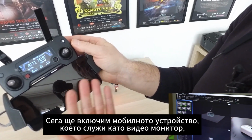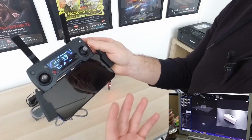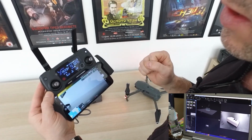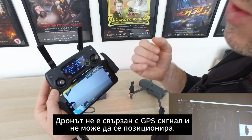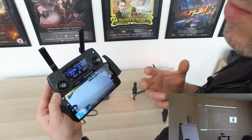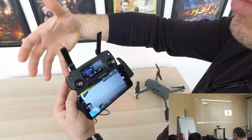Now we will include the mobile device that serves as a video monitor, that is, to see what we are shooting. And here is very detailed information about the connection between all devices. The gray icon here shows us that we have no connection with a GPS signal, i.e. the drone is not tied to a GPS signal and cannot be positioned. In general, it is not good not to be positioned, because you lose the ability to return with the home button.